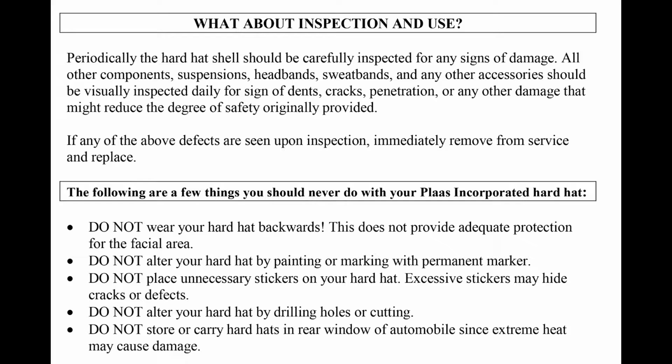Do not wear your hard hat backwards. This does not provide adequate protection for the facial area. Do not alter your hard hat by painting it or marking it with a permanent marker. Do not place unnecessary stickers on your hard hat.